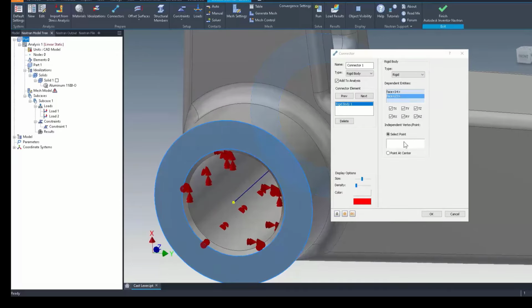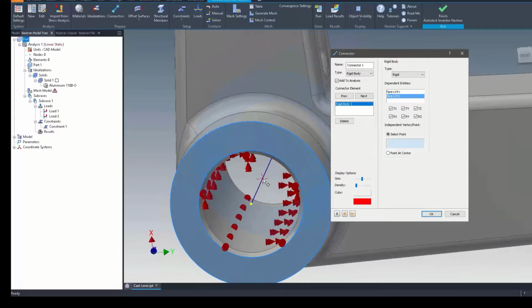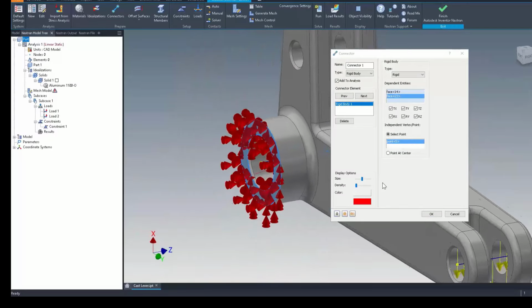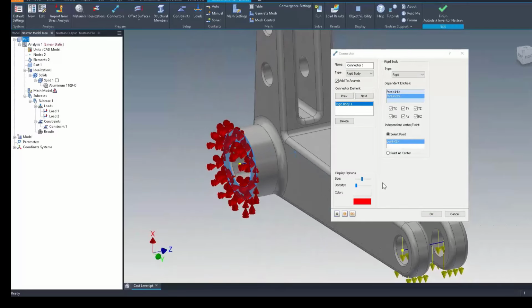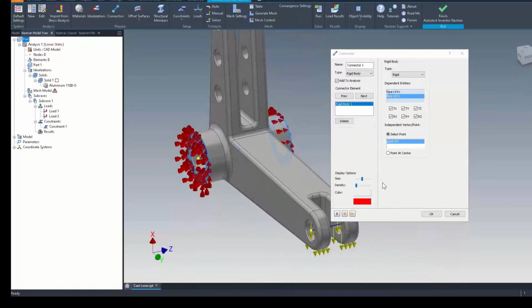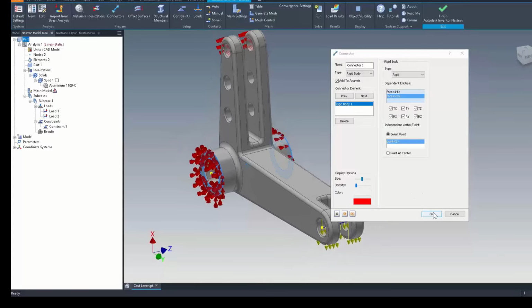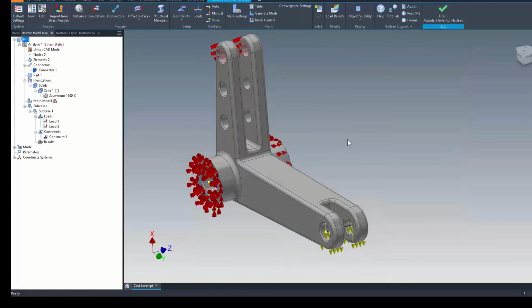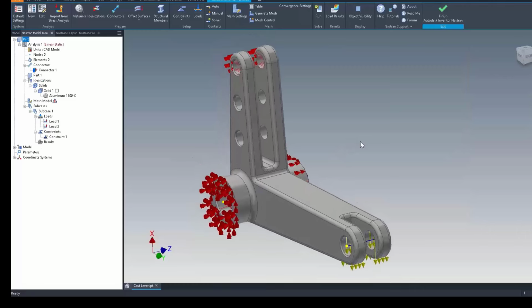on that main central shaft, and I'm going to lock down that work point. So that's going to lock that. Even though I put a constraint on there for the cylinder, it's actually going to lock the outer faces in conjunction with that cylinder. So it's going to make sure it doesn't twist and doesn't move, because doing so might skew my results. So now we're ready to look at the actual mesh.